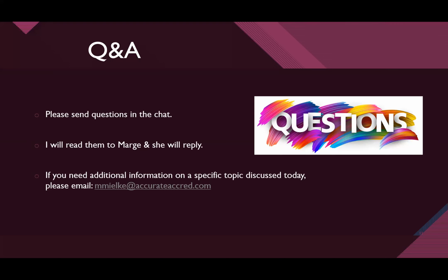We have another question here. Do we need to have any signage on the door connecting both buildings? Yes, you do. And you need to be sure that that door and that separation is 1 hour. They can't just punch any old door in that wall. If your ASC is abutting a clinic space, that whole wall should be a minimum of 1 hour. Depending on your state code, it could be 2 hours.